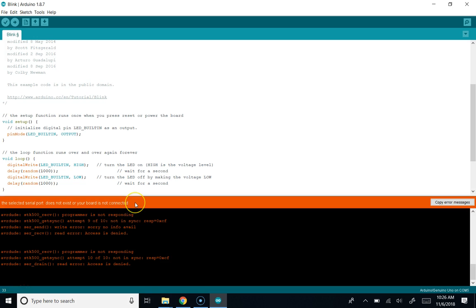Let me pause this. Okay, so this is obviously the most annoying thing, that you have to wait for it to kick an error. In this case, I pulled the board, but this will also happen if you lose connectivity with the serial port. It might happen if you try to push code to your mouse. But usually, what it'll do if it tries to push code to your mouse is it'll just sit there for about 5 minutes, and then it'll be like, yeah, it didn't respond.